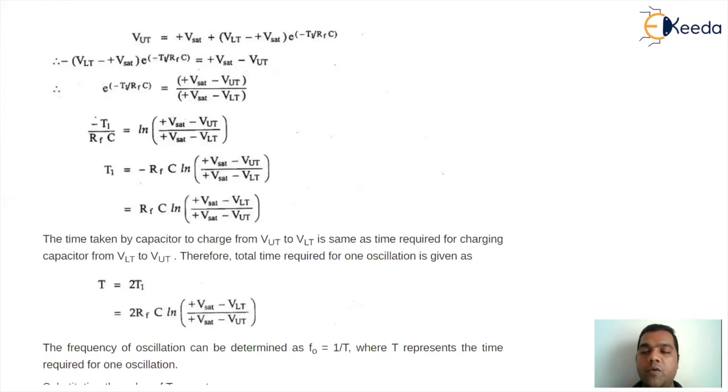So this is how you can understand that the op-amp can be used as an oscillator, or we can say a square wave generator. If we give the waveform of the capacitor to a smoothing filter, that waveform can be converted into a triangular type behavior, or a sinusoidal type behavior also. That depends on the way we are trying to go for the wave shaping of the signal. So overall, this circuitry was specially designed to generate a square wave type output from an op-amp circuit. Thank you.